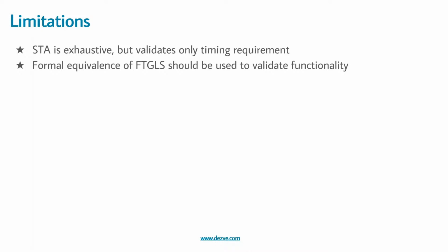And since we are doing it statically, we could always do it on the entire circuit at the same time, because we break the entire netlist into timing paths, and each timing path is analyzed independently.